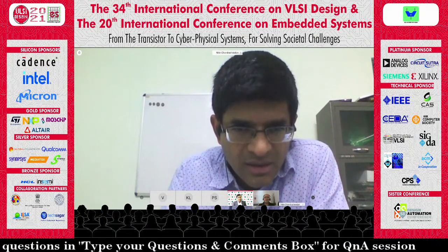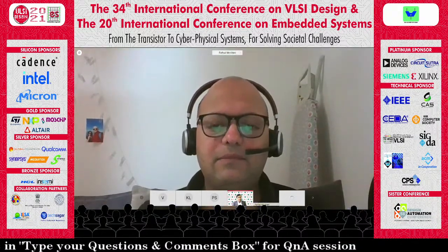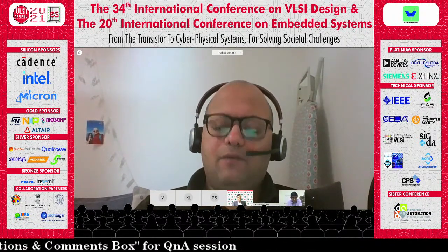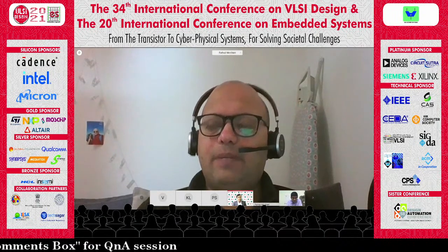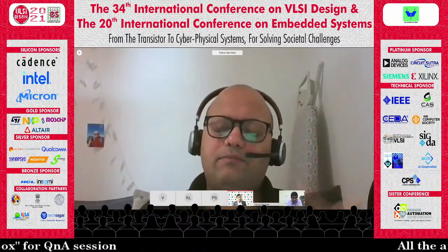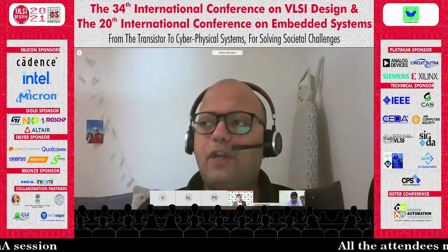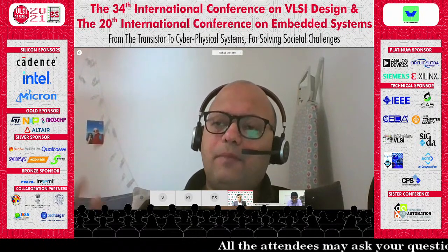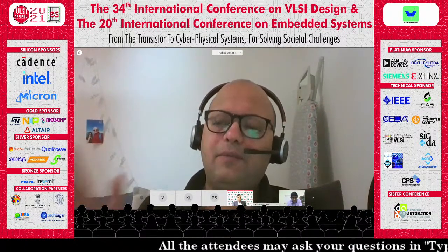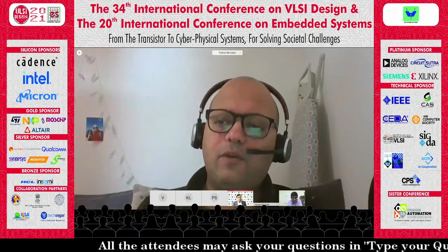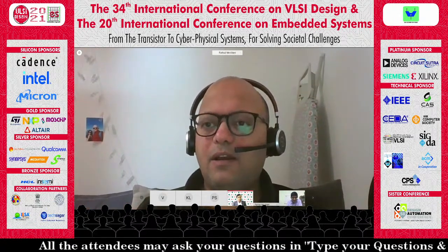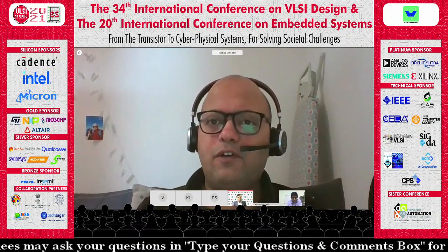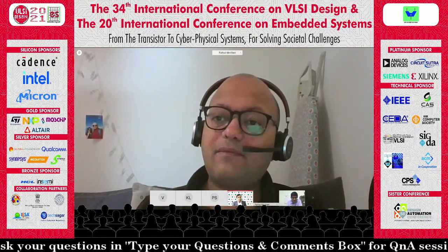Yes, this is a framework that was developed by my colleague in France at UPHF, and there we injected bit flips at different positions, exhaustively. What we ensured is that, let's say if we are injecting a bit flip at the 5th bit from the LSB, then we inject at the same place for float and POSIT both. Right, because when you have a bit flip, the bit flip is not going to know what format your data is. Sure.